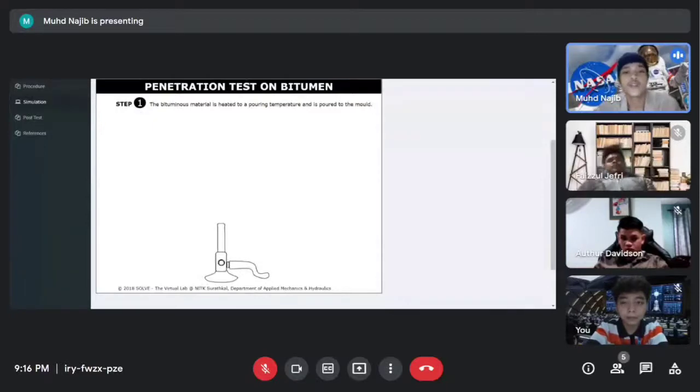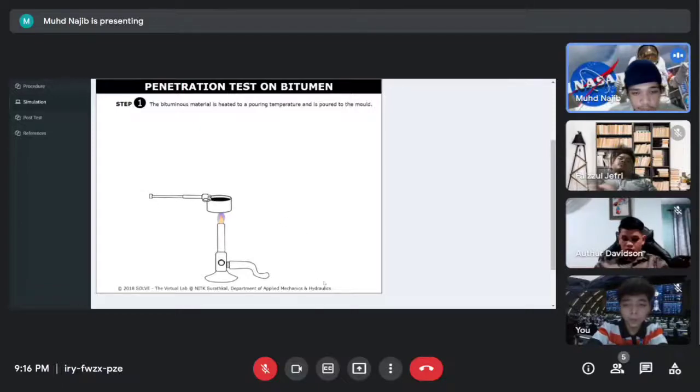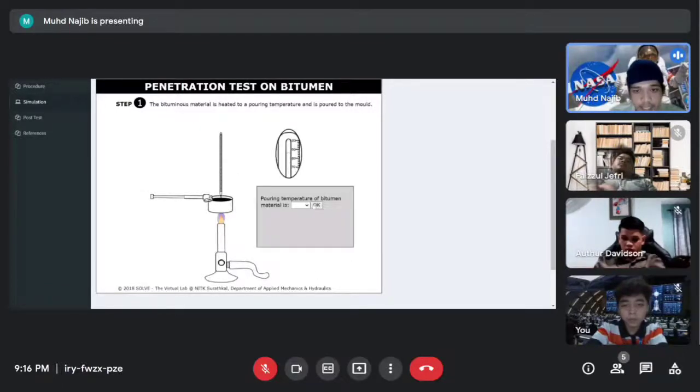Thank you, Muhammad FAIZZUL. So my name is Muhammad Najib. I'm going to present about the procedure. As usual, the specimen is prepared in a sample container exactly as specified. Before that, we heat the bitumen first at 90 degrees Celsius.